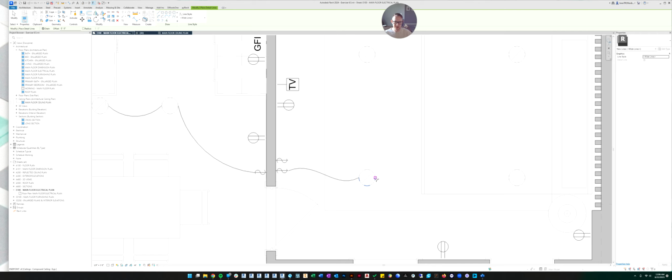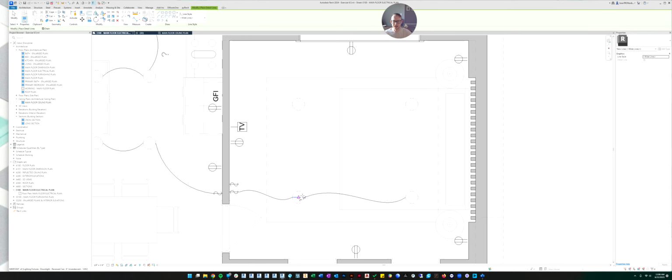And then escape will make it so it will disconnect from the first one so you can start the second one. So some people like to do this, spline command. Some people like to do this S shape, and they do their lines like that. And then I'll hit enter to finish the spline. And then I have to go get the spline command again. For some reason, it's not like an arc where you can hit escape and it'll disconnect it.